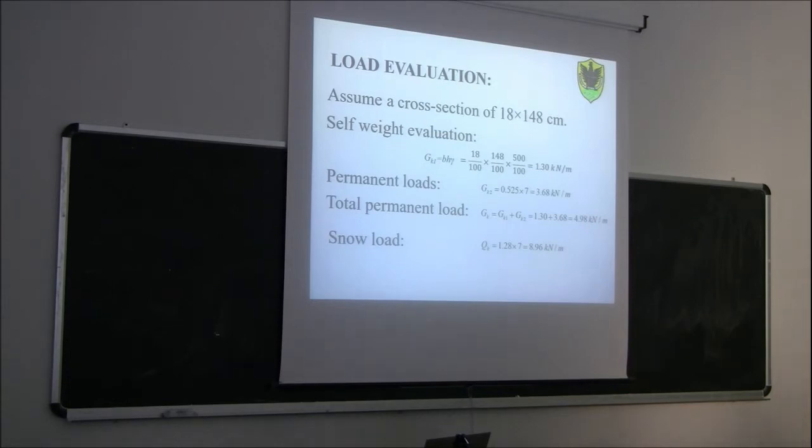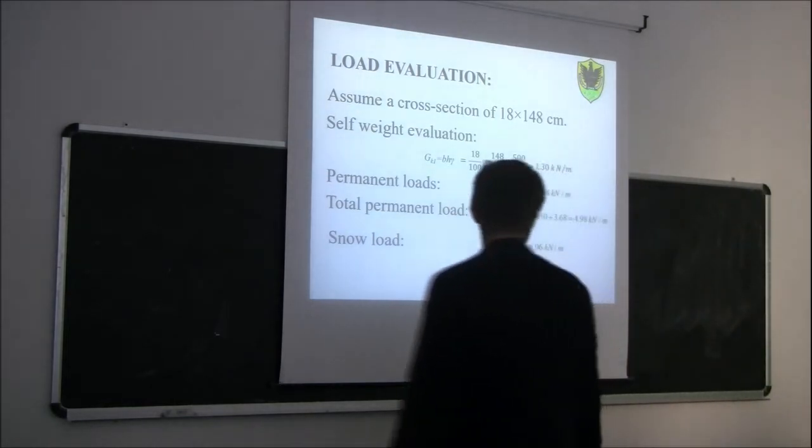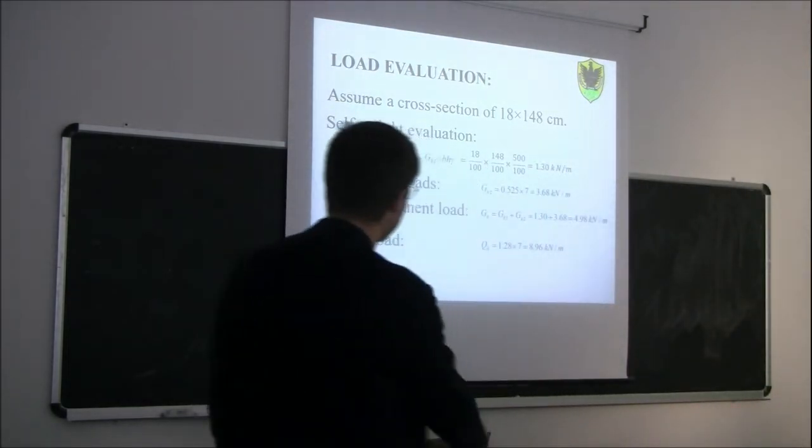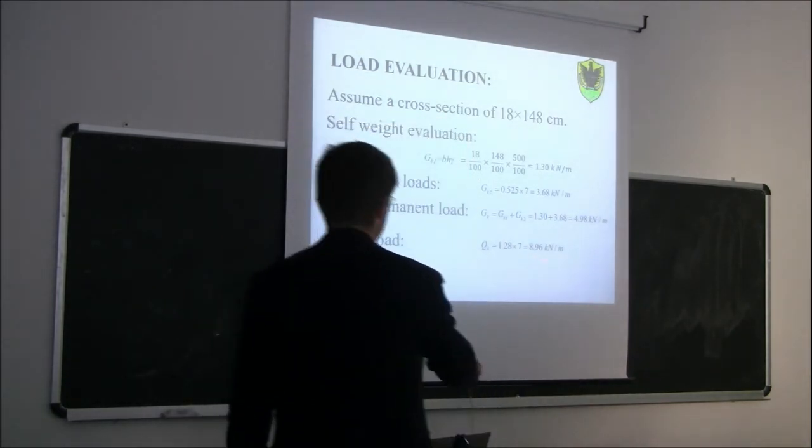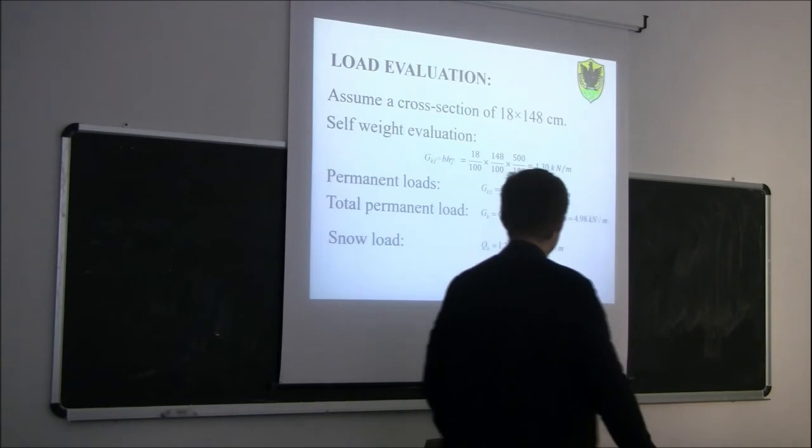And then we calculated the snow load. The snow load was already given, 1.28 kilonewton per square meter. Again, we need to multiply by the tributary width, so the spacing between the beams. So 8.96 kilonewton per meter.